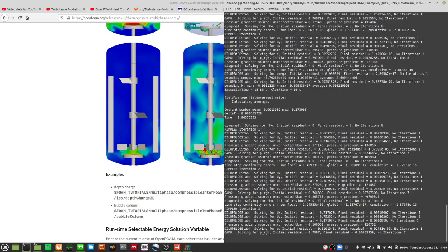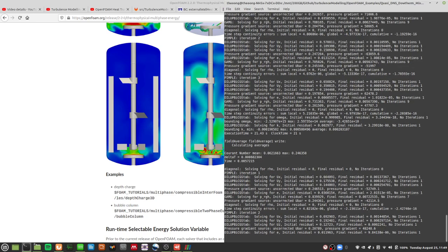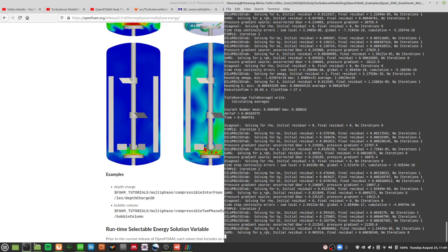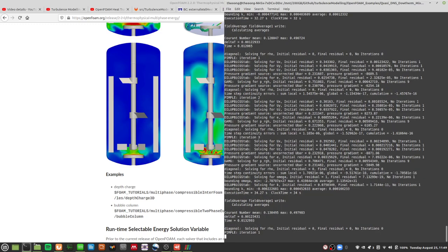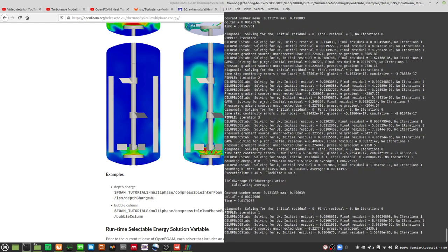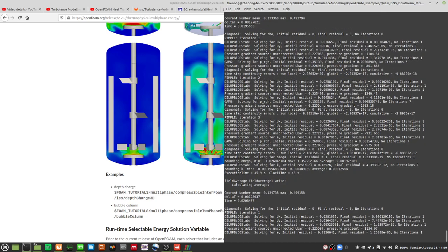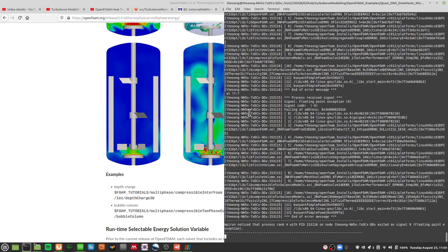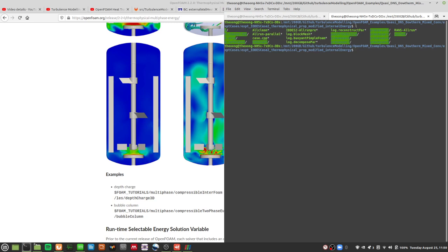Now this again is a promising result. It is not fully tested, but it's actually pretty good compared to what we were seeing before. Of course, the caveat again is that you're taking out the natural convection altogether, and that is actually pretty problematic. But it's better than nothing. There is some way that you can simulate forced convection, and that's actually good enough. And this is actually an LES grid. Let me show you. Control-Shift-T for a new tab here in Linux Mint. Let me show you the mesh.